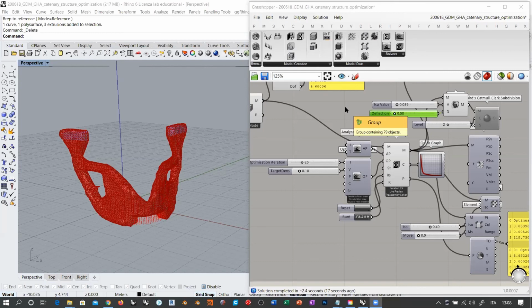Well, actually, it's my bad, I didn't express myself correctly. The problem with Millipede is that in order to get a good result, remember that Millipede is quite old, maybe it's not as efficient as Topos. In the case of Millipede, you have to increase the number of iterations quite a lot to get a proper final result.